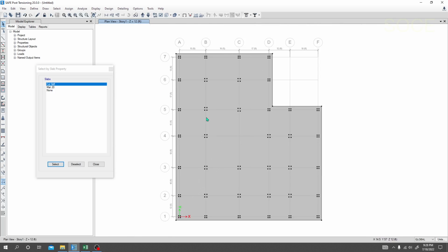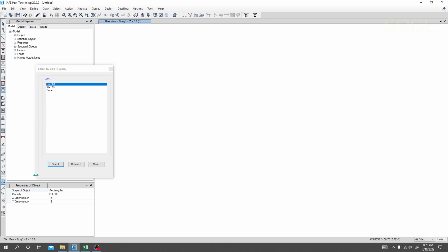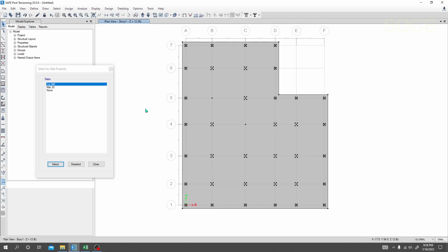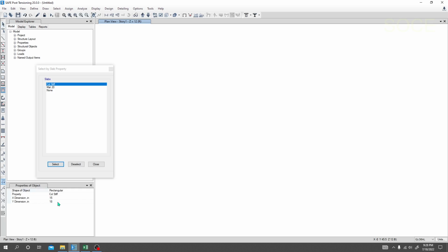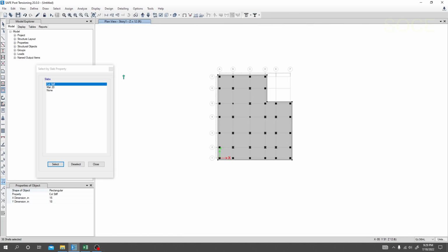And now I'll select that one, and I'll draw again here column strip 18 into 12, and I'll just draw here. Okay, now it's done. Now if we go for column strip, so here it's available, and sorry, here we also need one, then here. So everything is okay. Now again if I go for it, just see everywhere the column strips are being selected. Now I'll close that.